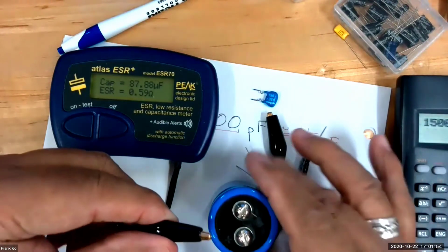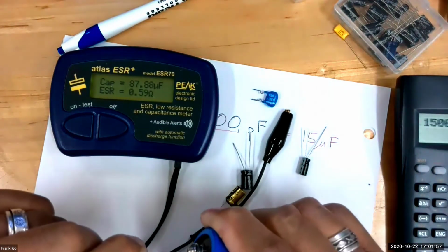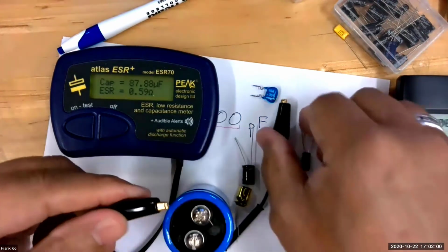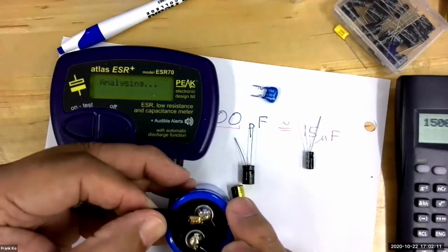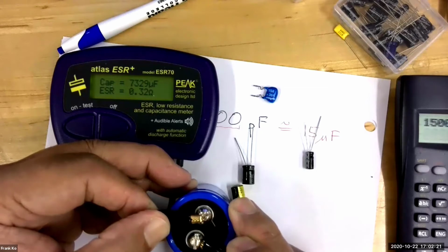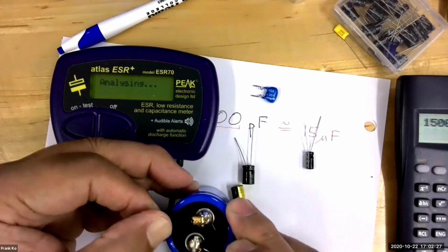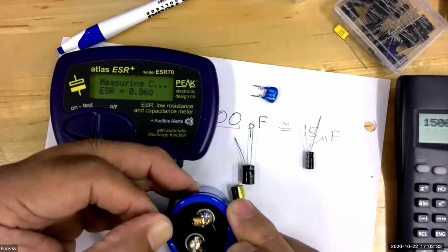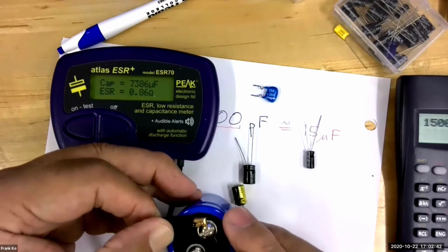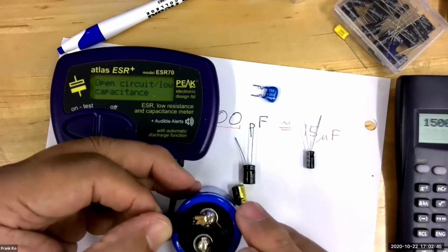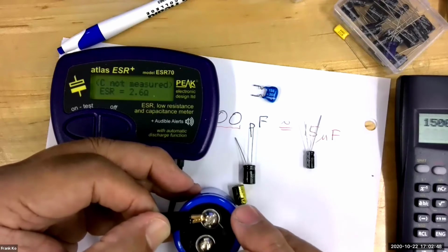This is supposed to be, what, 6,000 microfarads? Now, I'm not sure if this is too large for this meter, but let's see. I've not done one this size. I think I'm just going to have to touch these. Okay, touch and hold. Oh, leaky. How about the other way? Okay, it's supposed to be 6,000. Where are we? 7,329. Boy, I'm glad we measured this before we put this into a circuit. So before we utilize capacitors in any electrical circuit, you want to make sure we measure them, so we will find either a physical capacitor that is closer to your ideal result or use the measured value, okay?